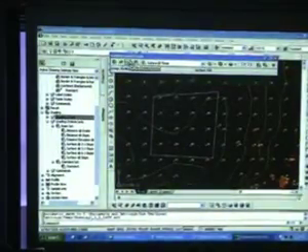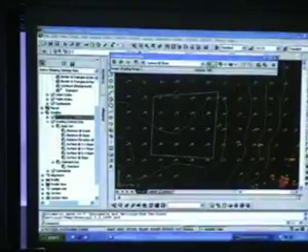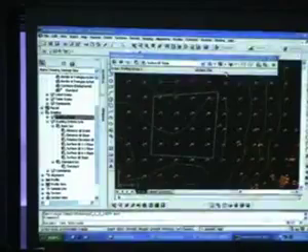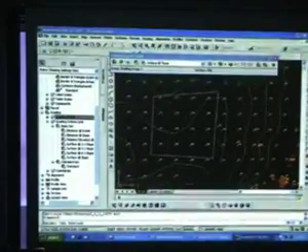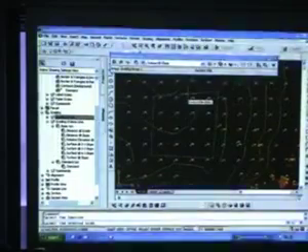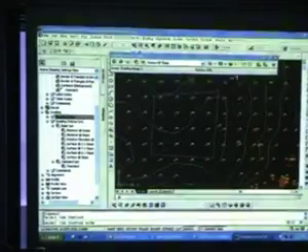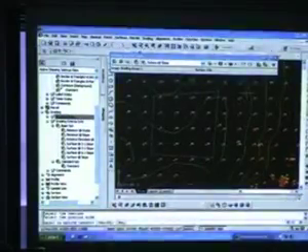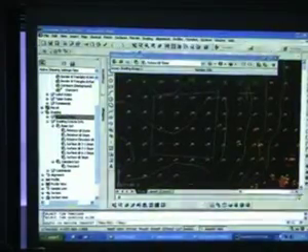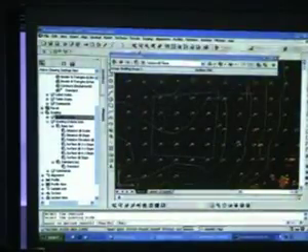Like you just go from one icon to the next. So after we finish this, we click on this one now, create grading. Okay, they'll ask you to select the feature. Select the polyline you've created. Select the grading side. That means you want the slopes to go on the outside or the inside. If you want it on the outside, just click anywhere outside. And they ask you to apply to entire length, do you want the slopes to be along the entire length of the platform? So let's say yes.